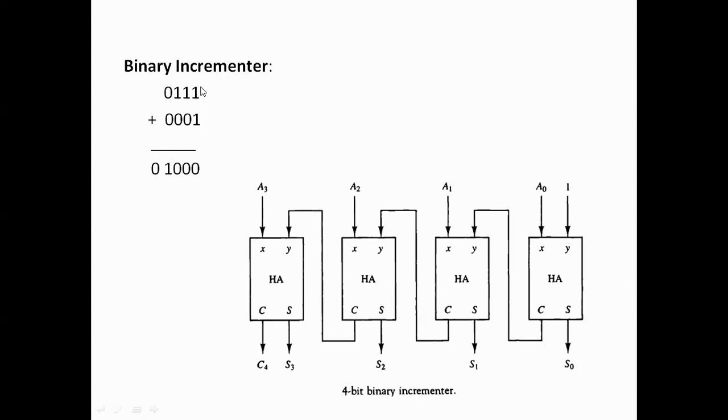So we can clearly see here we are adding 2 bits, which means we need a half adder. At this step, we again are adding only 2 bits, because adding 0 is not a must. All other bits will always be 0, so no need to use a circuit for this. At this level, there may be a carry and this bit, so adding the carry and this bit needs a half adder.